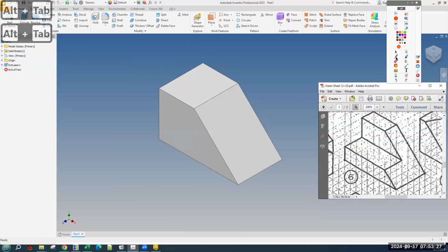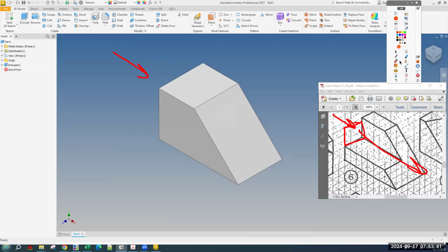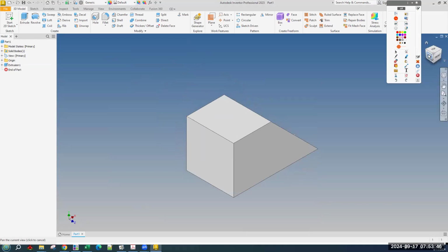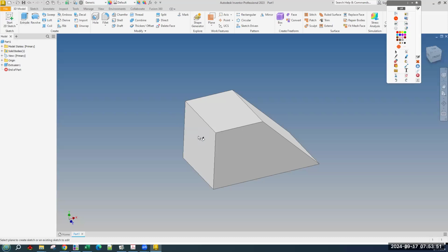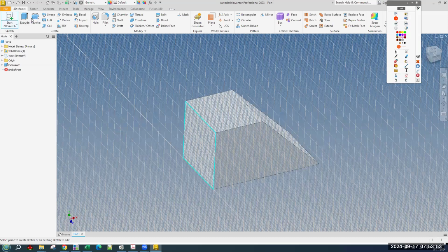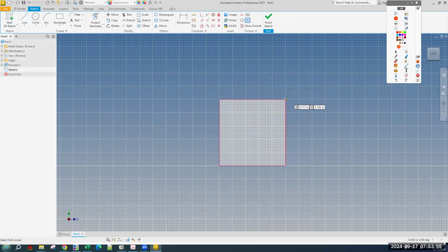And the way we're going to cut out this ledge is by, on the left side, which is this side, we're going to make this shape, a 3x3 rectangle, and then cut extrude all of it. Okay, so we need to look at the left face. And we'll start a sketch on this face and get a rectangle that snaps to the top corner. And we'll just make it look about right.